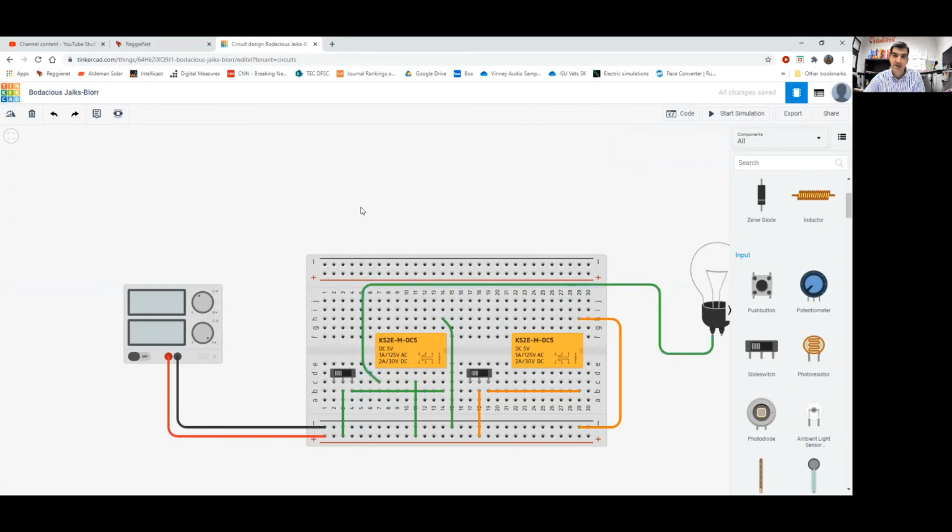Okay, that looks pretty good, but I need to use some different colors here. So the third rung, I will make, how about blue? Yeah, that looks good. There we go. All right, so that's almost half of it. So I've got from the power supply to the common of the contact, and then using the normally open contact and going to the input of the light bulb.